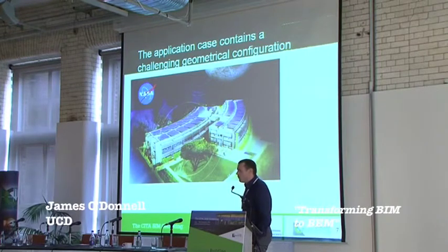It's a very difficult building for one reason: the facades are essentially concentric circle segments with a center point a couple of hundred feet away from the topmost facade here. And what that resulted in was a series of non-orthogonal interior wall intersections that had a number of different problems. So I talked to different people yesterday about tolerances, and 20 mil or 10 mil seemed to be an acceptable tolerance within the industry, but unfortunately we have a 0 mil tolerance for this process, and that's one of the limitations, and I'll talk about that at the end.